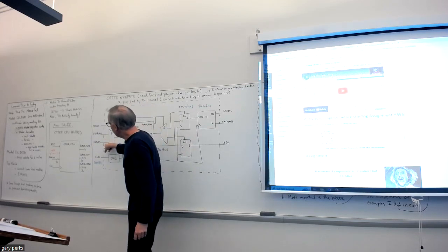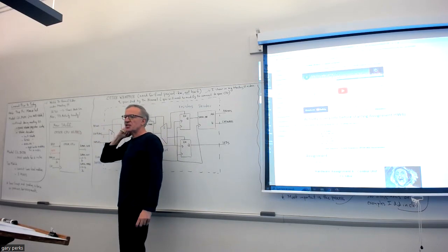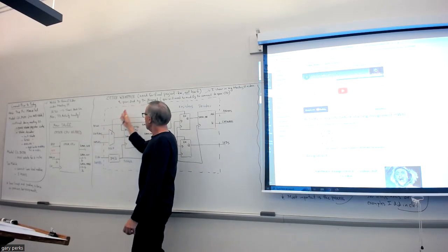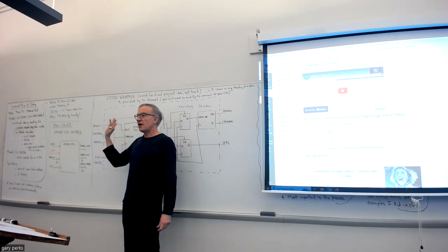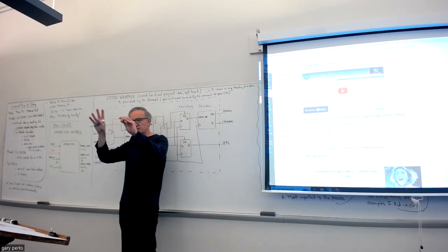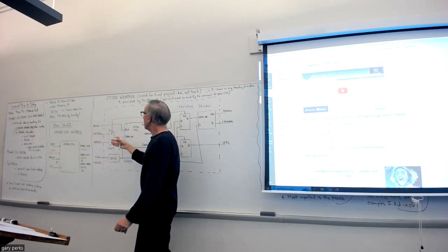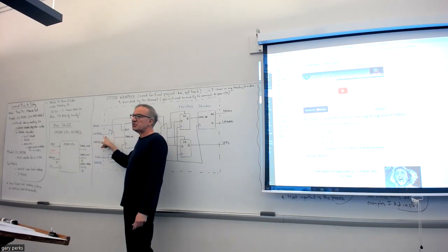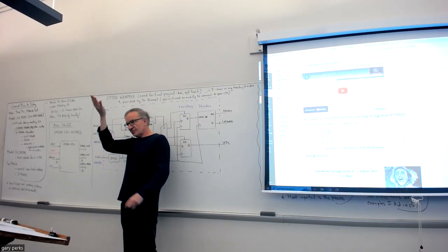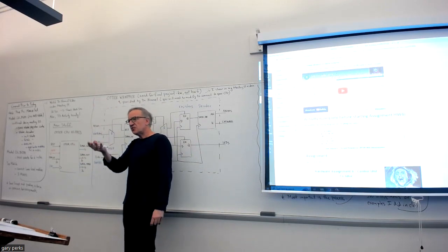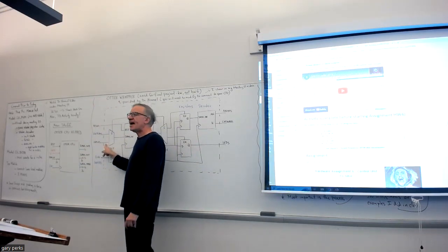Now, you might notice that the other input here to this MUX is just labeled inputs, very general. That's because the default code of the wrapper just has switches as an input to this MUX. But the code has the flexibility where you could add inputs here. You could add more than one more input, a number of inputs.